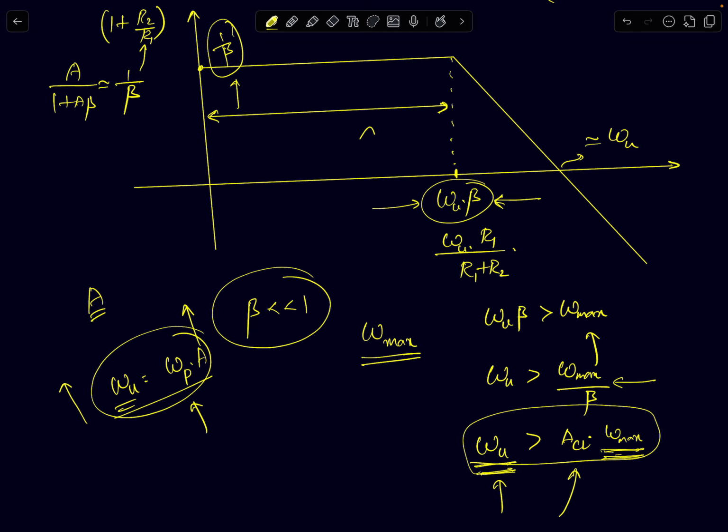But right now this is a discrete op-amp case wherein you don't have much control over designing the op-amp. You are just an embedded designer who's going to pick an op-amp based on the specifications that you read from a data sheet. If you know the maximum frequency until which this circuit has to operate, and you know the feedback factor or the closed loop gain, then your UGB has to be greater than closed loop gain times the maximum input frequency. If you meet this condition, you're good.